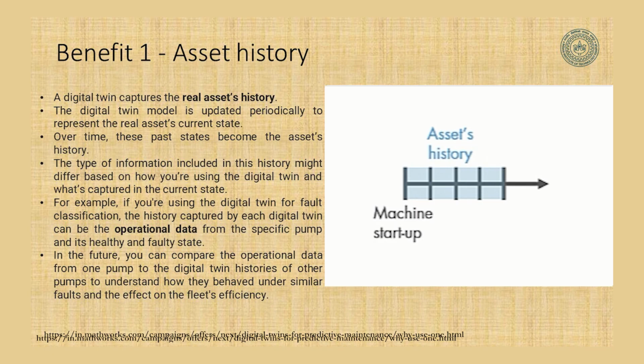Okay. Maybe this fan fails after 5,000 cycles, this one failed after 5,200 cycles. So, you can make some comparisons, and that can give you some average usable life for each fan. Okay. So, that then tells you, okay, I need to plan a replacement in 2 years time, 3 years time, 4 years time, okay, on an average. So, that kind of useful information can be had from a detailed asset history.